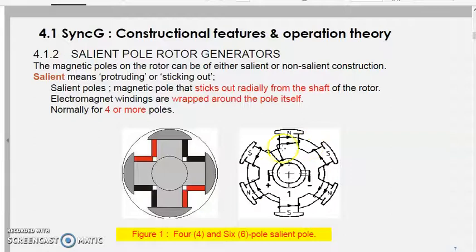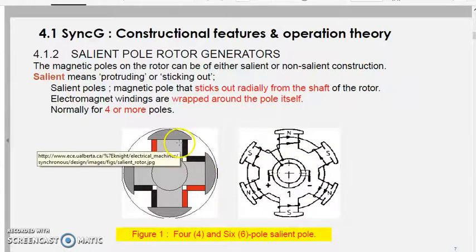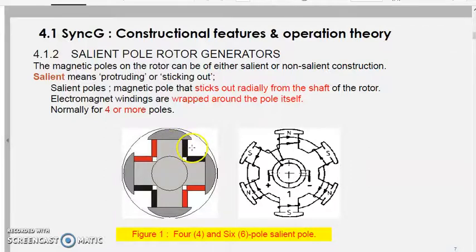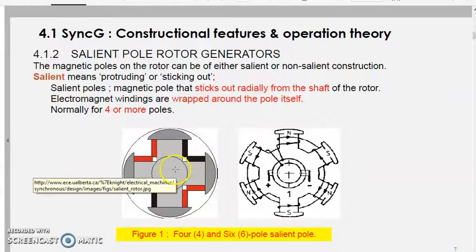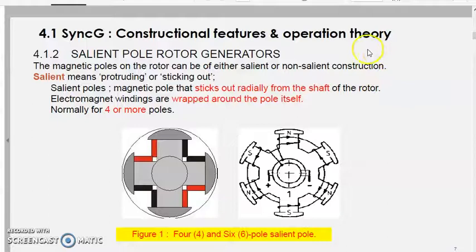You turn the shaft and the rotor. Then if you put more poles, the rotation you need to turn the rotor is much lower compared to the fewer poles, which require higher speed to produce the same frequency of terminal voltage to the grid.